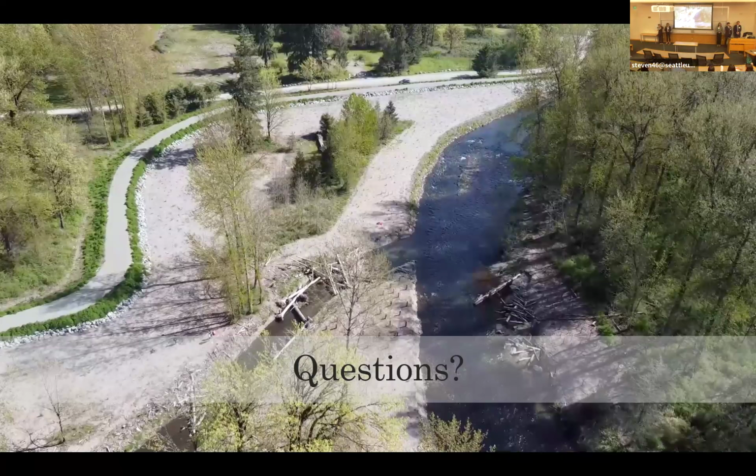Yeah, so the Manning's roughness coefficient was actually manually input into the model by King County. So one of our solutions that we outline in the report is changing this Manning's roughness coefficient, especially at the mouth of the side channel, to account for the flow that we actually see. It's just a way to model the friction of the flow. How did they get the Manning's roughness? I'm actually not sure of that, to be honest. I just know that it is an input of the model and that one of our recommendations is to change that in the future for similar projects.